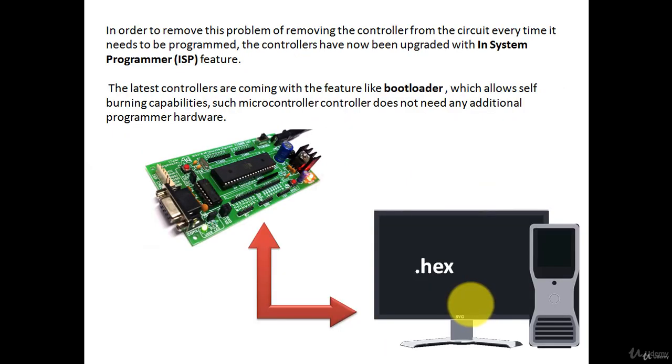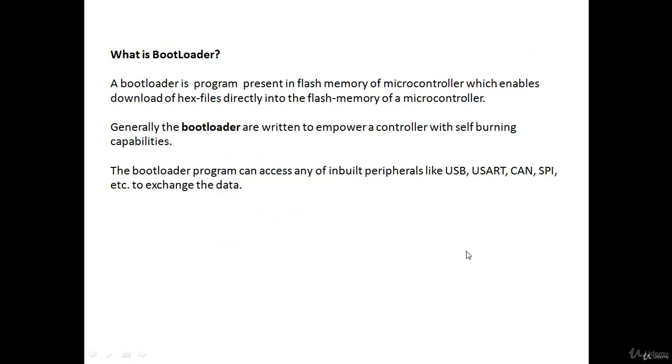Please note the communication between the PC and the microcontroller can be through a serial port, USB port or parallel port. Bootloader: a bootloader is a program present in the flash memory of the microcontroller which enables the download of a hex file directly into the flash memory.